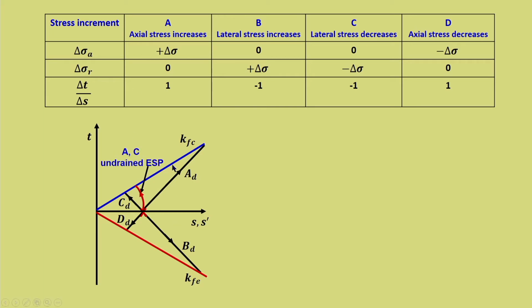So, this is the undrained stress path for A and C. Why is it written A and C? Because that represents compression, and the effective stress path for cases B and D, which represent extension, is given by this. Now, where does it go and fail? That is governed by the A value. If the A value, after substitution, is such that 1 by 1 minus 2A is the slope of the effective stress path, then when you substitute the A value,